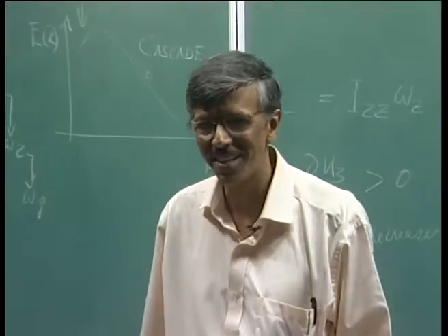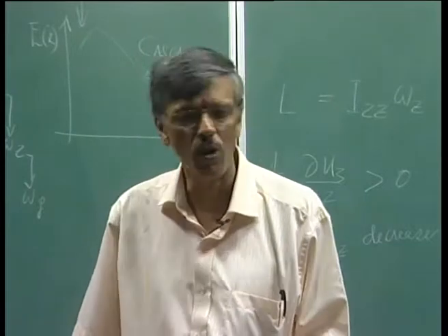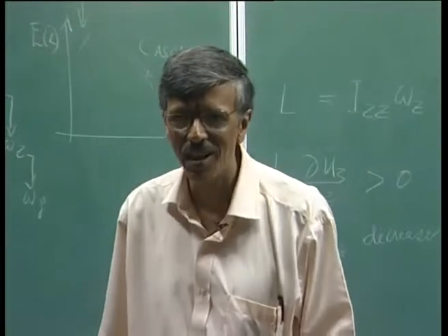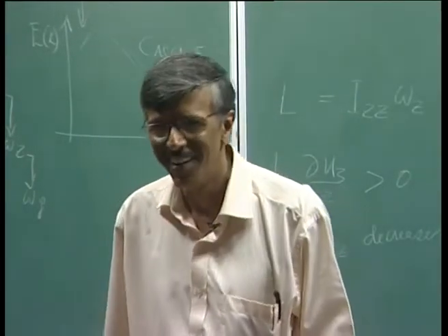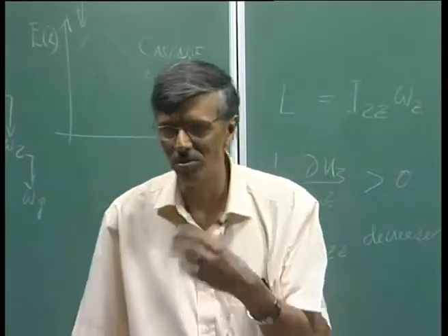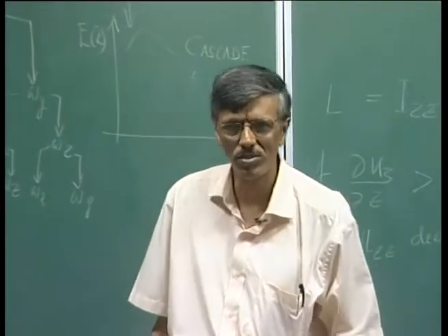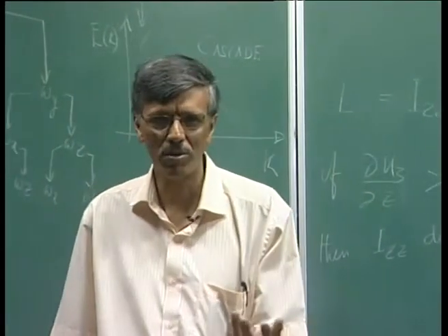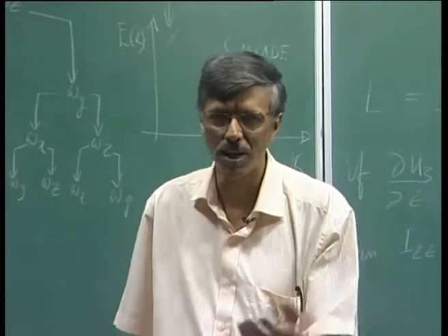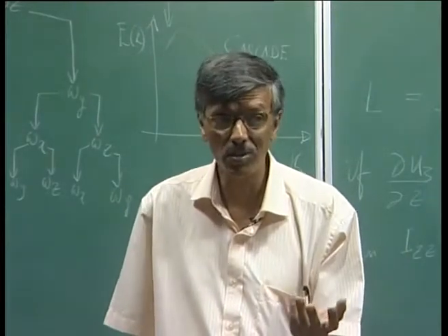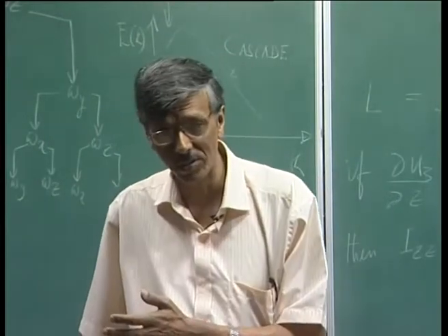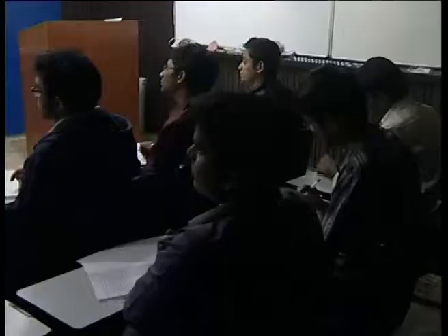Whenever you look at source material, people only say, oh, turbulence has to be 3-dimensional, it cannot be 2D because there is no stretching. So, how is the energy spectrum explained? But we have lots of counter examples. We have seen Kelvin-Helmholtz instability is one, where bigger eddies were breaking down into smaller eddies. So, that means what? And you know Kelvin-Helmholtz instability is more dominant in 2D flows compared to 3D flows. So, here are counter examples people conveniently forget.